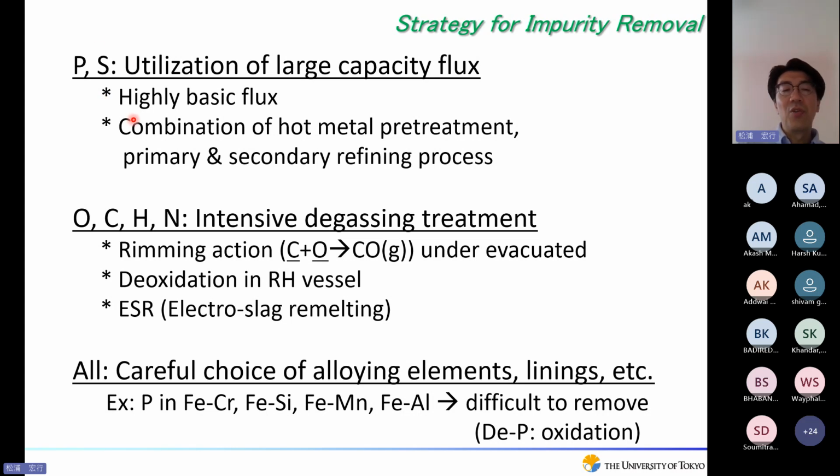So in that case, you need to think whether the additionally coming sulfur or carbon can be removed after the alloying process or not. If we cannot remove any particular element after that alloying process, you need to avoid it, and then you need to pay some additional fee to buy relatively excellent grade ferroalloys to avoid the contamination.